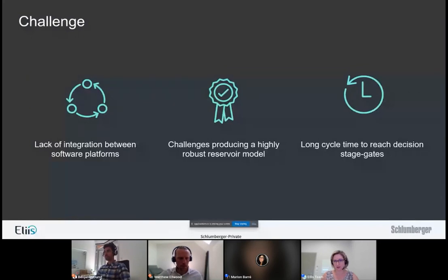Okay, good. Thank you, Ben. I've got a question for Matt. Does this work with all types of structural framework, or only depot grid, or also pillar gridding or staircase gridding? Yeah, this is a good question. The structural framework process in Petrel, as we highlighted, is a way to produce a representation of the subsurface structures. Underlying that is a tetrahedral mesh representation, and we use that in gridding workflows. There are three options in Petrel. The first is to create a depot grid. That's a simple process where you can define the gridding resolution and produce a model that represents the full subsurface framework because it's a cut cell grid. But optionally, you can also generate a stair-step grid using a similar UI. If you want to produce a pillar grid, it's a little bit more involved. You have to convert the resulting model to the pillar fault model and then regenerate the horizon model. But it is possible to do so.